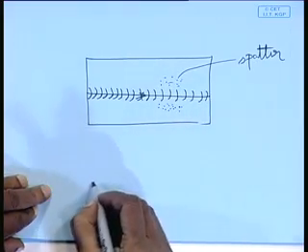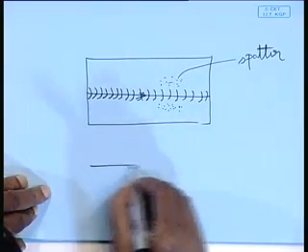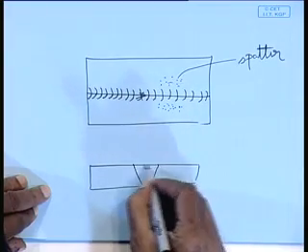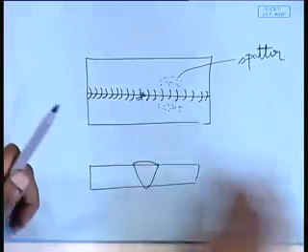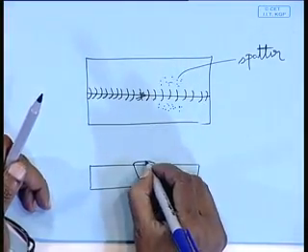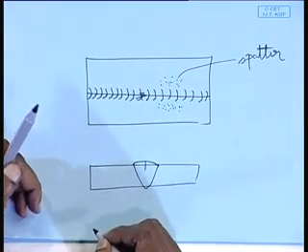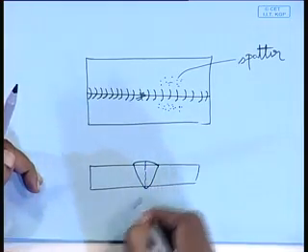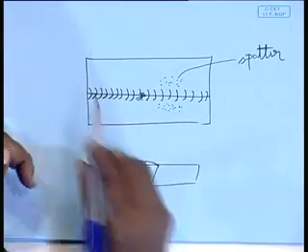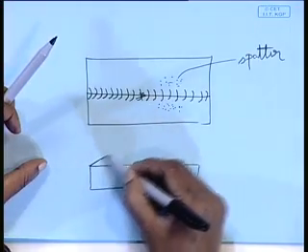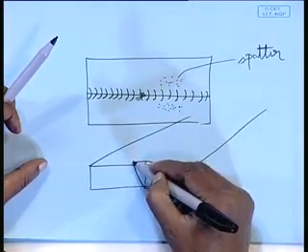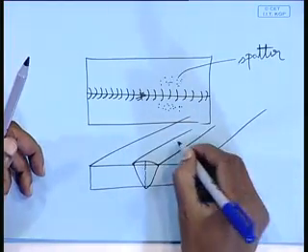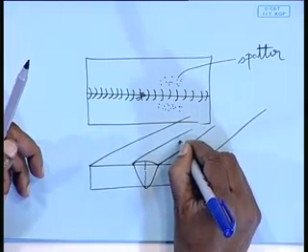And then you have the so-called surface crack. Say a welding has been done, there is a weld bed, and you see a crack in the surface. A crack can be a vertical crack. This crack can be a through and through crack. It can be on the surface, a localized crack.